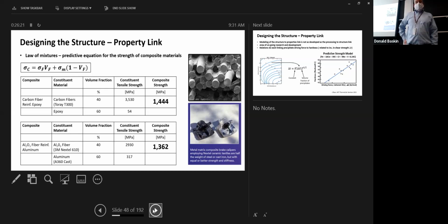In this case, it was reinforced locally, just where we had the reinforcements, which was in the bridge area, kind of in here. The disc of your disc brake goes in here. There's pads, it squeezes together. Anyway, you don't need to know too much about this, but just understand it's selectively reinforced. In this case, the rule of mixtures actually worked pretty good because the fibers were really straight.